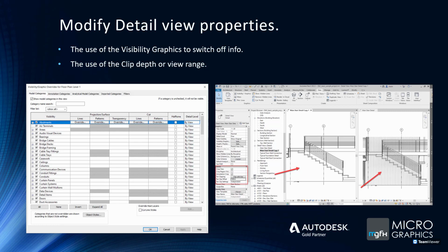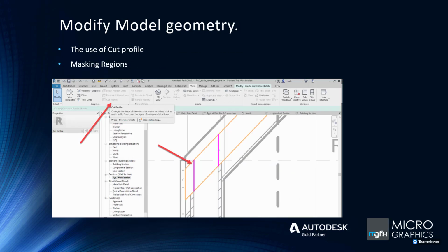And that'll help. Then looking at the specific model geometry, this is more used in the hybrid environment. We'll talk about that, but you can use the physical layers within each object, like walls or roof. You can actually use the cut profile tool to remove parts of those layers, but only in the section, which means that it's not physical 3D modeling.